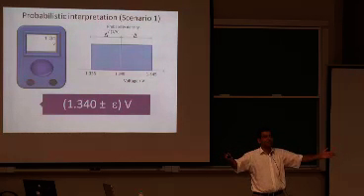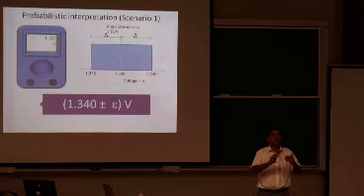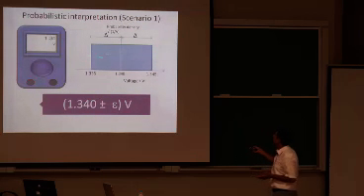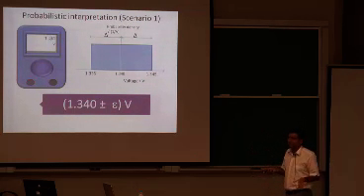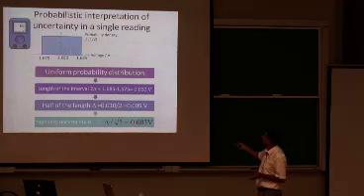It's easier to deal with 0.001 than 0.0009. So we have to stick to some level of simplicity in calculating uncertainties. We do not want to make our lives overly difficult because it's difficult anyway if you would like to calculate uncertainties properly. So this is our probability distribution function. It's a uniform probability distribution function. So if this is your reading, this is the distribution function that you specify.